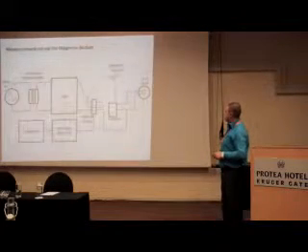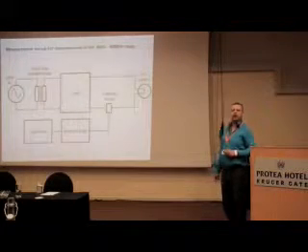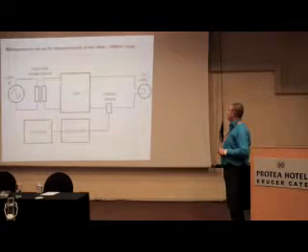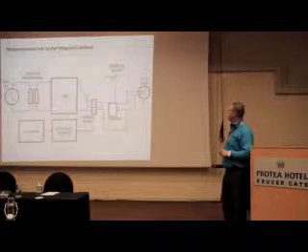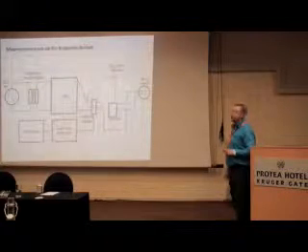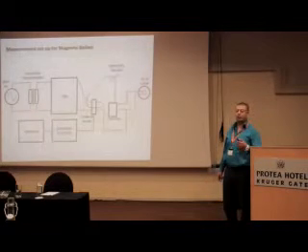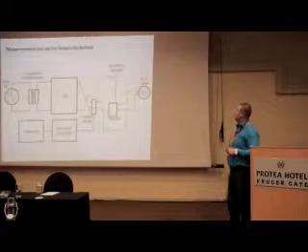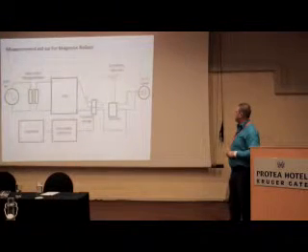This one is used only for CFL, LED, and plasma. This one is used for those who use magnetic ballasts. For metal halide lamps, high pressure sodium, and mercury vapor, we use electromagnetic ballasts, and we use an igniter to start the lamp itself.